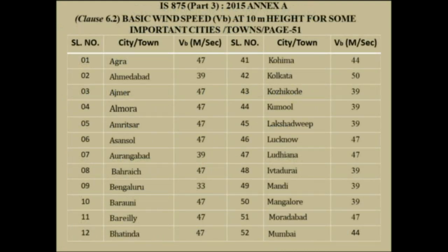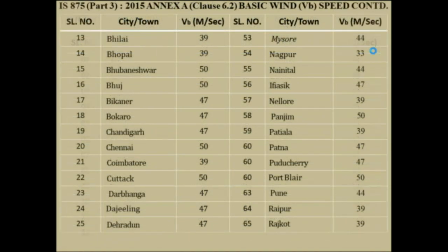This is our basic wind speed table. Our zone is Kolkata. This is the city or town, and the basic wind speed is 50 meter per second. These are the continuation of the table.